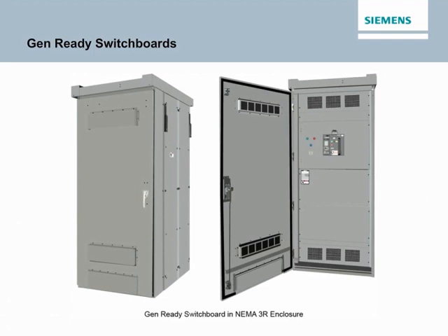Siemens generator switchboard features include all standard switchboard features, Crouse-Hinds Quick Connect cam locks for quick primary connection method, standard mechanical lugs suitable for Type W welding cable for a secondary connection method, NEMA 1 and NEMA 3R enclosures, trapdoor on NEMA 3R enclosure to maintain rating with cables connected, labeled phases and ground connections, bus connection between generator breaker and plug-in quick connects, mechanical interlocking with normal breaker, removable screw cover for covering quick connects when not in use, and may be provided as a standalone unit or hard bus in traditional switchboard lineup.